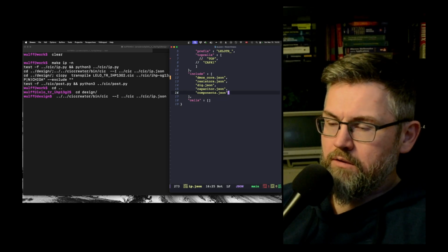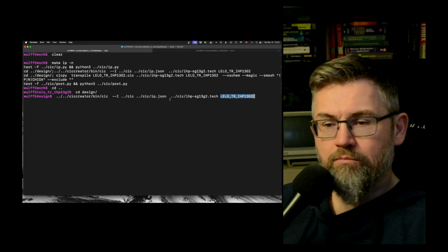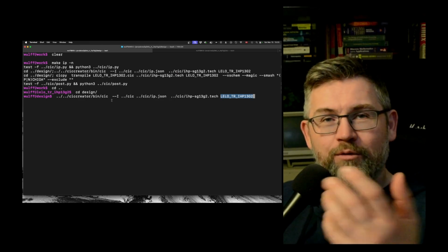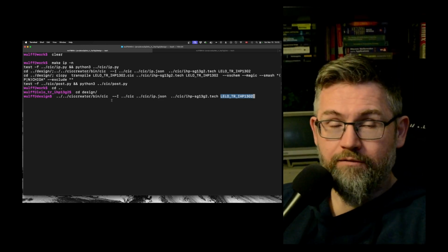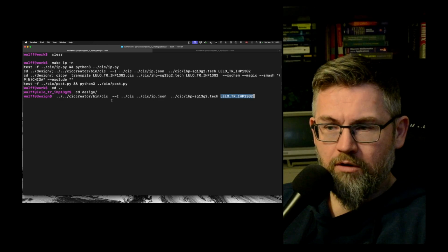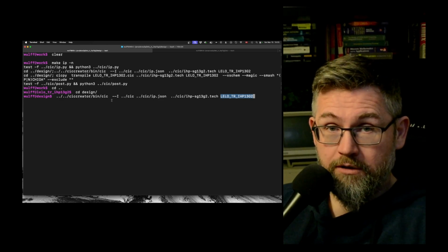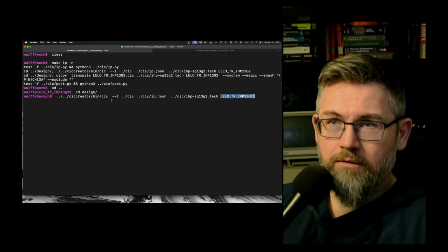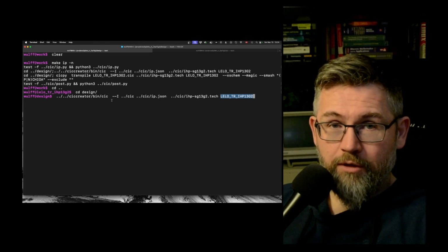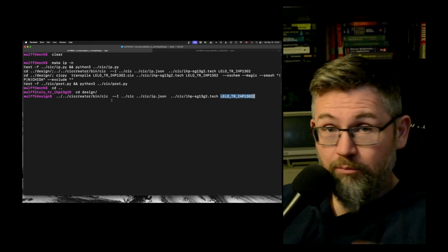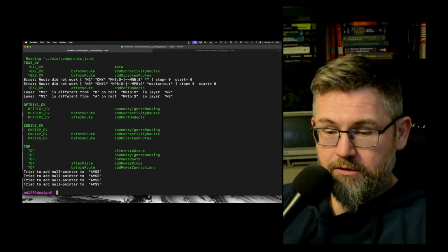Now, notice that it doesn't specify the SPICE files. This compiler, CIC, will automatically find the SPICE files, because what it expects is a JSON file to describe how to do the routing and a few other things. And it expects a SPICE file to describe the connectivity and the actual components. It also does the placement from the order in the SPICE file. I've written a paper on this. You can go and have a look at that. So let's run it. And now it's done.